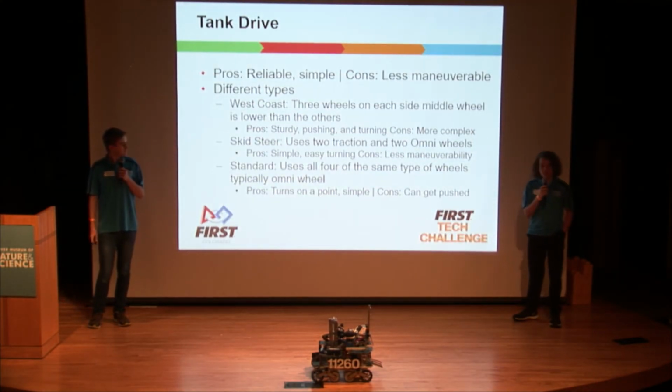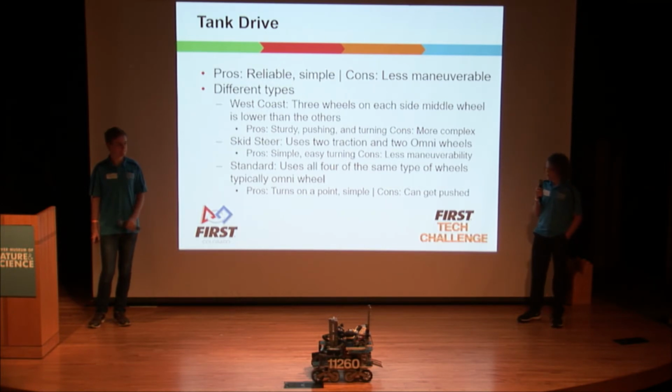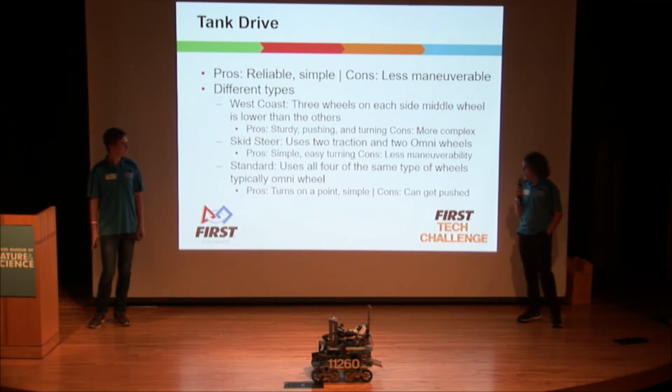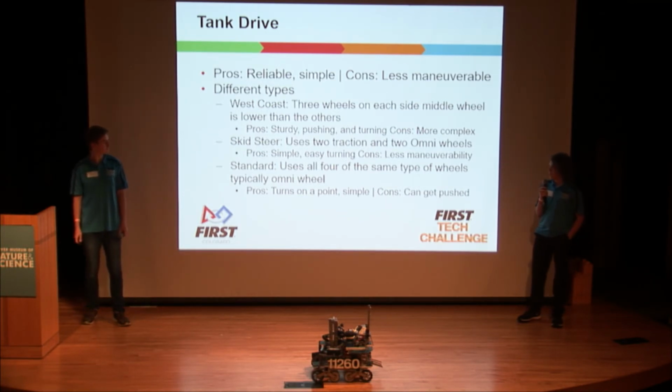So the first type is the tank drive. The tank drive is the most simple chassis and one of the most common. The pros are that it is very reliable, but it is less maneuverable than other types of chassis. There are 3 different types of tank drives.